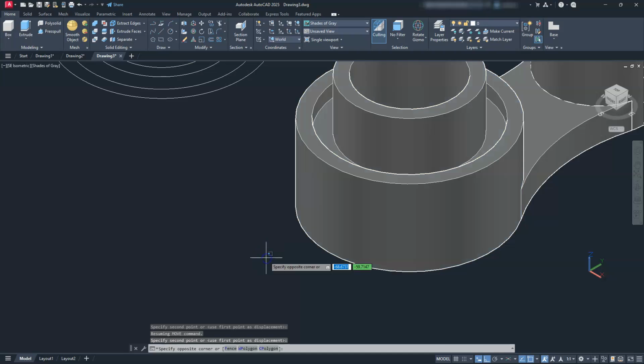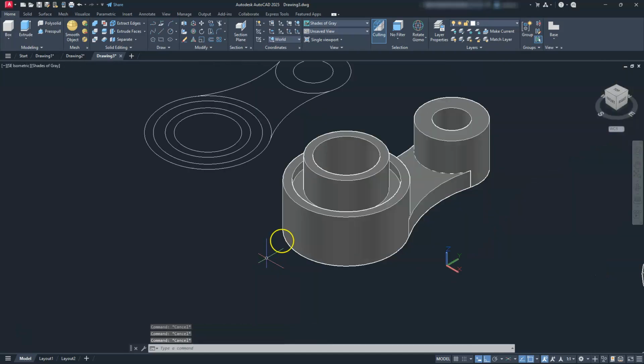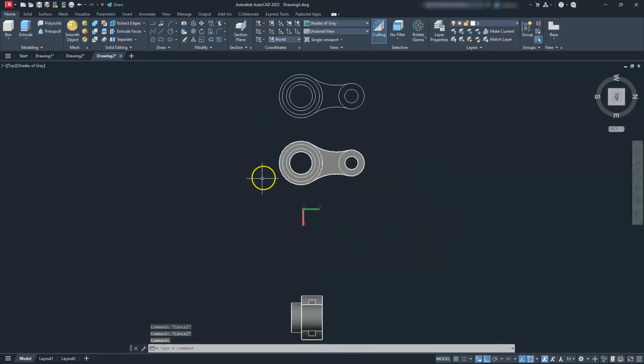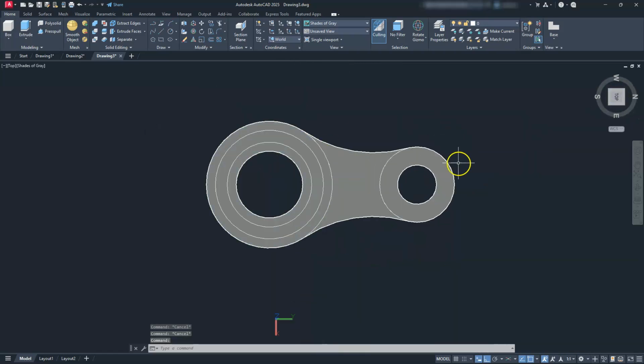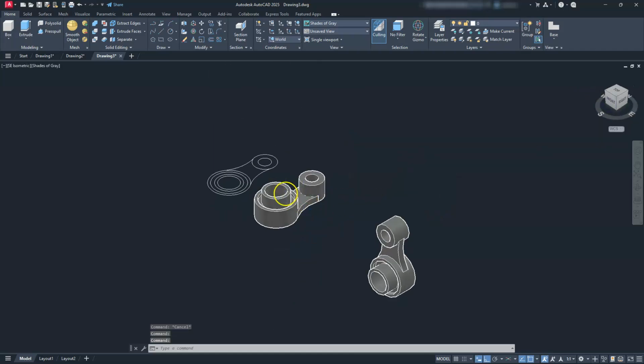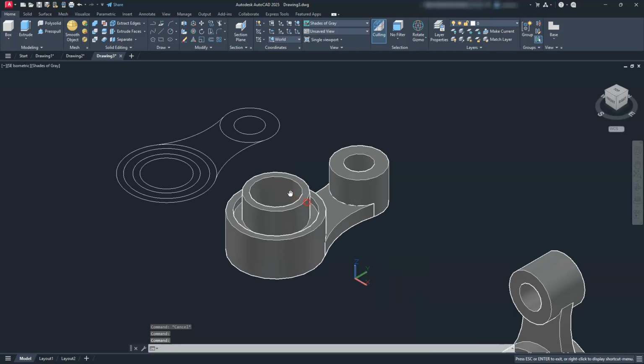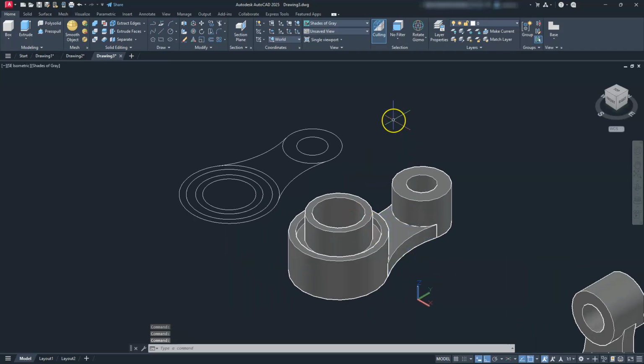All right. So remember that you want to make sure that these look correct. What I mean by that is if I select on the top view, you can see that it did make that shape that I'm looking for, right? You can see it's all tangent out. Let's go ahead and click back to here. What I'm going to do next is move this shape going up a distance of 10. So let's switch to our move gizmo. Select that shape there, click on that blue axis there, type in 10, hit enter.